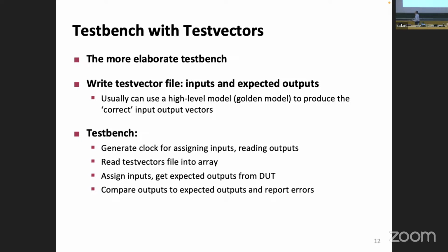I want to have a nice clock signal, maybe an initialization at the beginning that makes sure that we start from a known state. Yeah, so generate clock for assigning inputs, reading outputs, read test vectors, assign inputs, get expected outputs from the device under test, compare outputs, report errors, do all the dirty work for us.